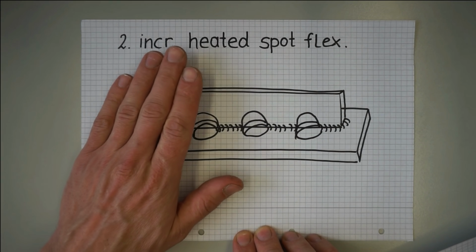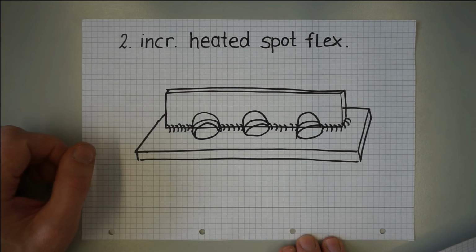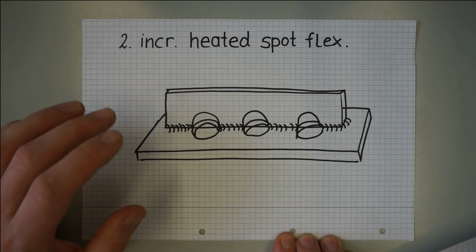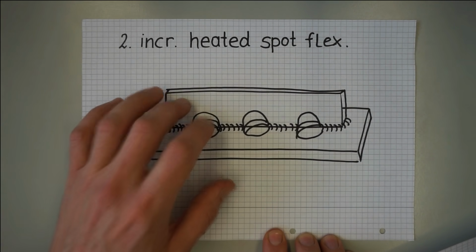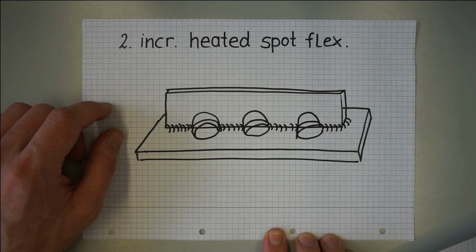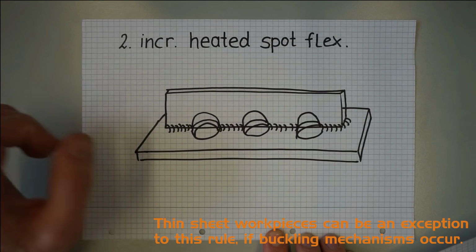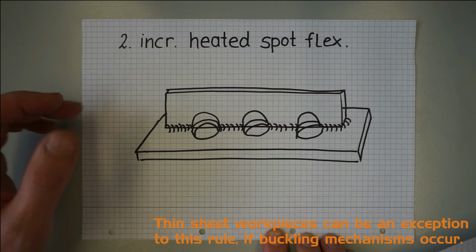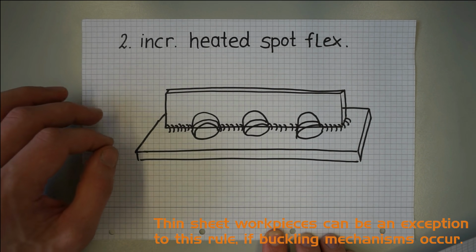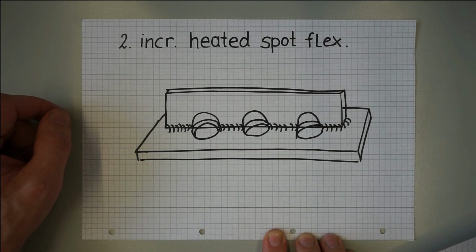And now at this point we must deduce something very essential, which is often misunderstood. According to the strategy, it's a mistake to clamp, fixture or jig a workpiece other than for tacking. Having it clamped, fixtured or jigged during welding increases the workpiece rigidity and therefore constrains the heated spot expansion more than necessary. This results in more distortion. I know, it sounds unintuitive, and surely welding table manufacturers don't like hearing it. But I will prove this with an experiment at the end of this episode.